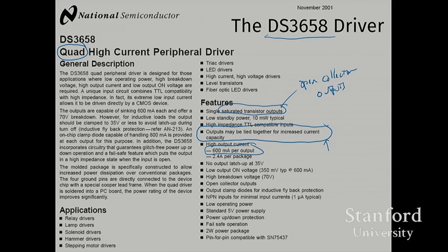If it tells you that the outputs can be tied together, it's telling you that there's been some effort on the design side to make sure that the specs for the 4 outputs on this one product are close enough together that they will share the current properly. And this is a thing that is, I would say, generally not true except when stated that it is true. So never assume that's the case.